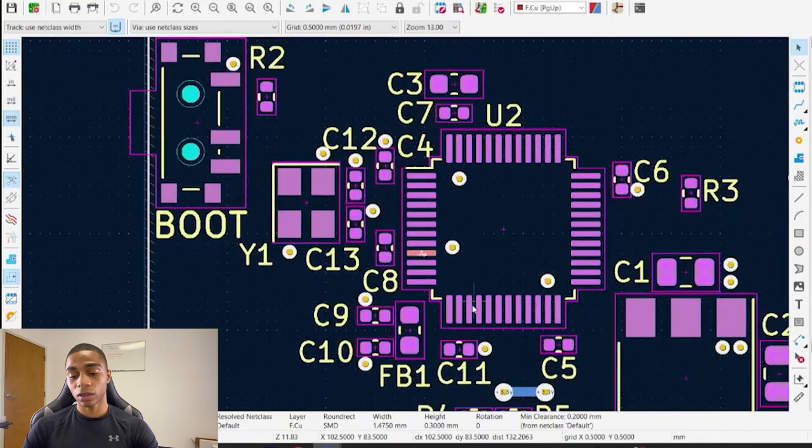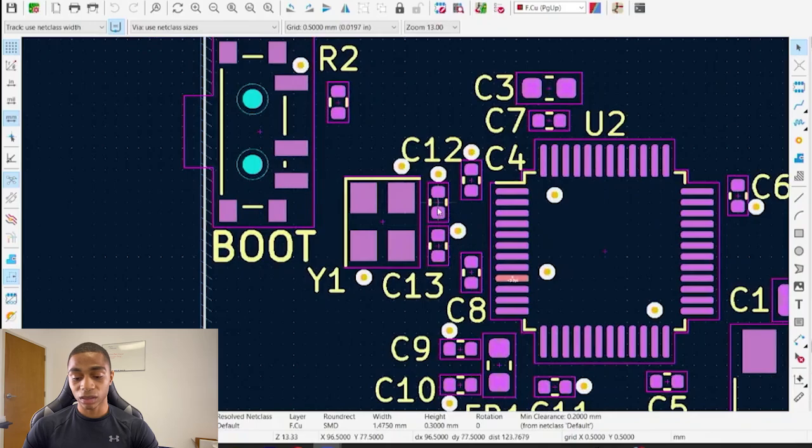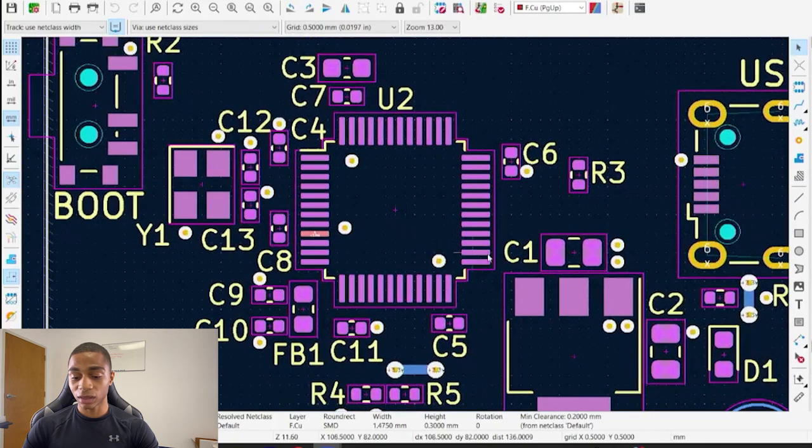So after we went ahead and placed our microcontroller, we placed our decoupling capacitors. Next, we placed our crystal oscillator, or our clock. Here we also have our 2 load capacitors close to our clock to allow it to operate at its resonant frequency. And we placed this first because, as we know, our clock is a sensitive component. It changes states 16 million times each second, right? So it's going to be a very sensitive component. It's susceptible to noise. It's susceptible to interference. So we wanted to place that first and give it its own space, and just make sure that everything was going to be working just fine with our crystal oscillator.